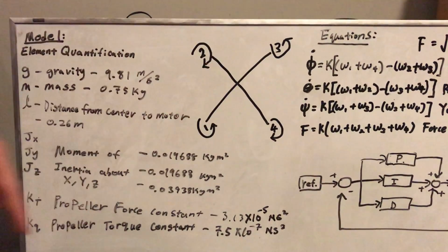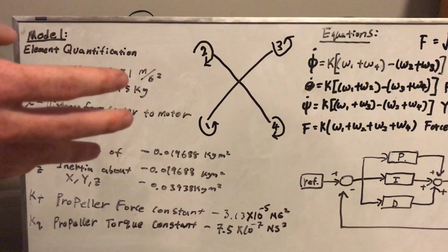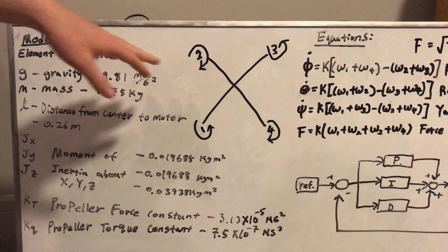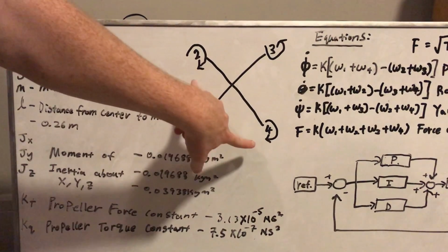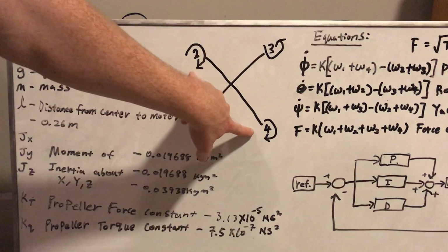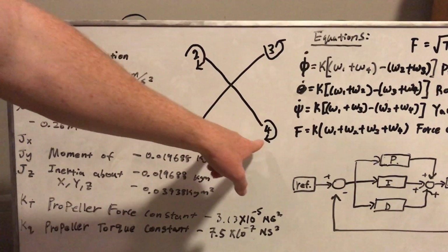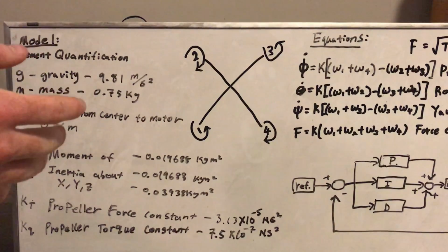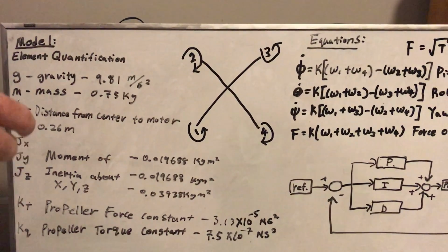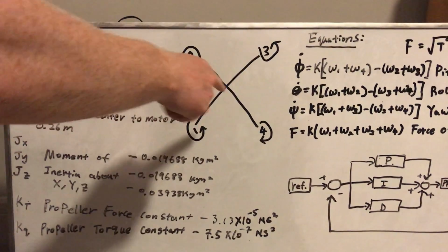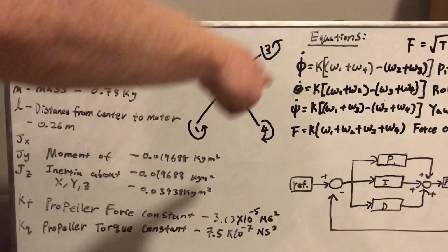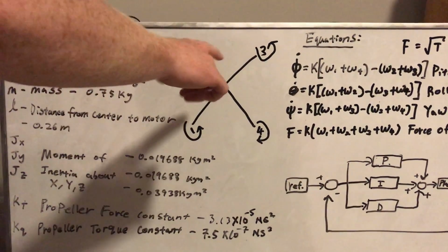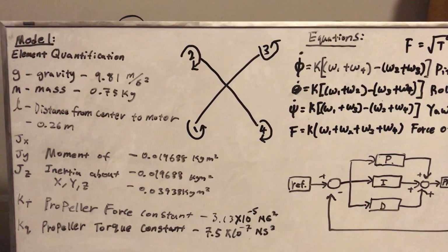It's usually four rotors, because it's a quadcopter, and each rotor has a propeller and a motor at the end of it. The propellers on opposite corners spin in the same direction, but they spin in alternate directions from the propellers directly next to them. This is due to momentum. If all the propellers were spinning the same way, the quadcopter would just start rotating in the air, and it would be really hard to control. So in order to cancel each other out, they rotate in opposite directions.